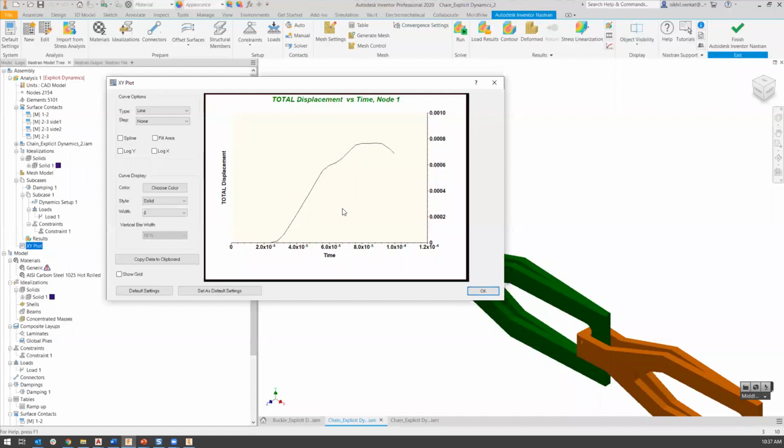So this problem gives us a good idea as to how that transition between linear behavior, which is what this is, and nonlinear behavior happens, right? Anywhere where you see a straight line between force and displacement tends to be linear behavior, and anything that is not a straight line tends to be nonlinear. So this is a great example of that.